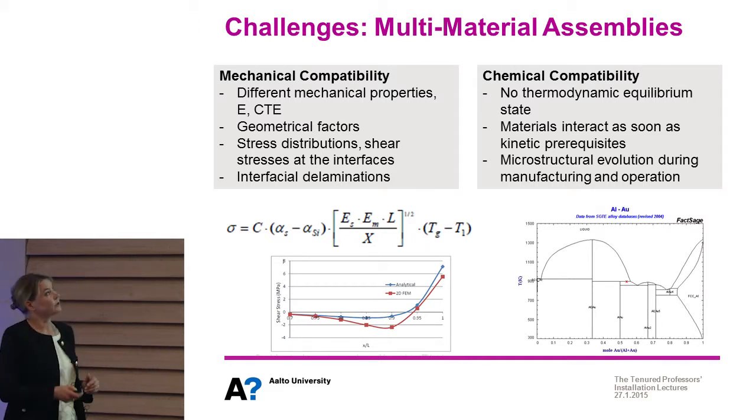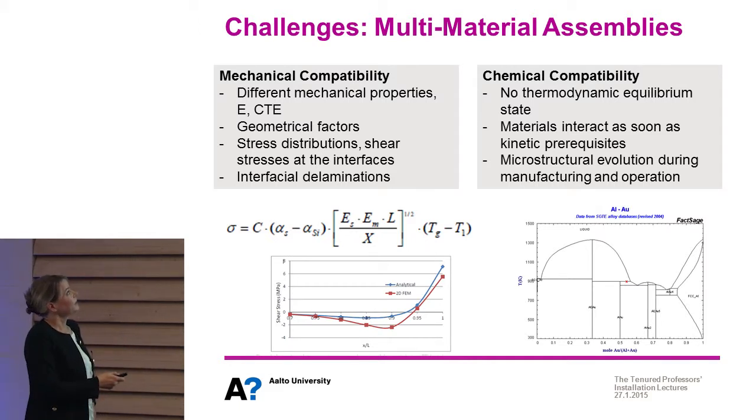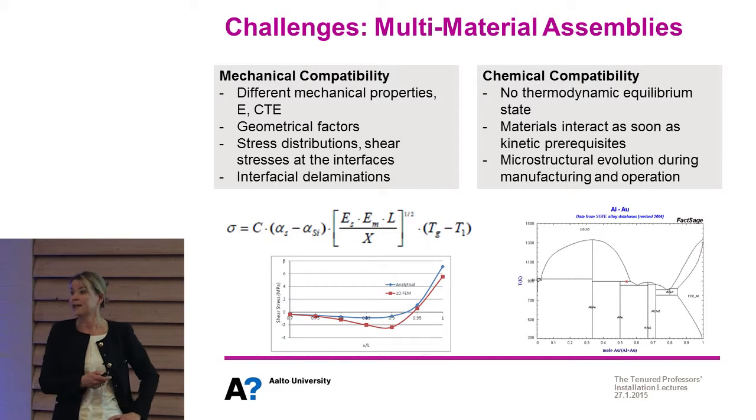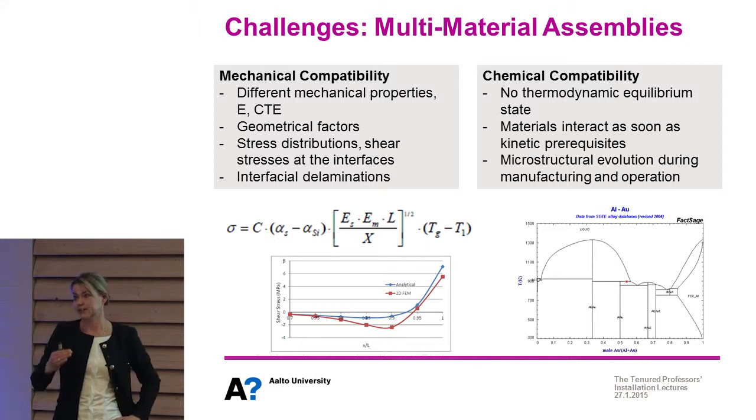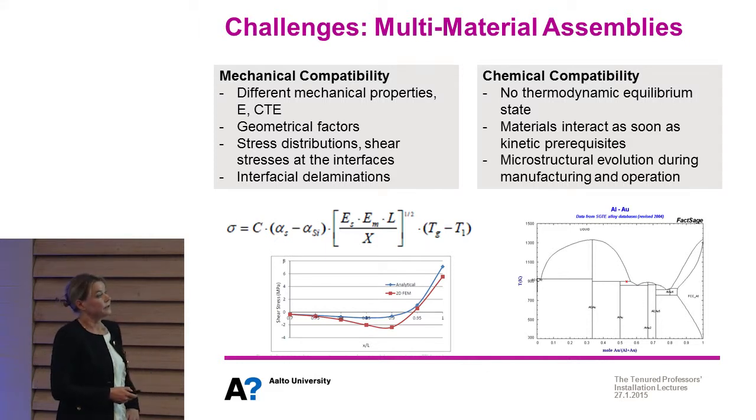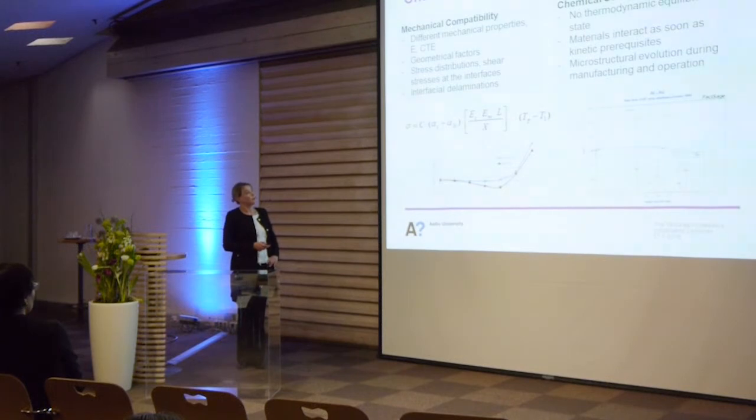And that is quite difficult because the mechanical properties of such materials are distinctly different, and when we expose them to high temperatures, for instance, the fact alone that the materials expand differently will generate high stresses between those materials and at design discontinuities.